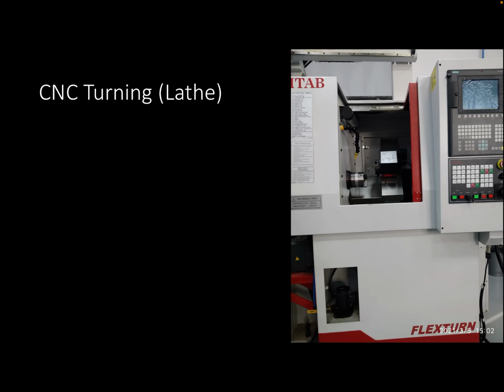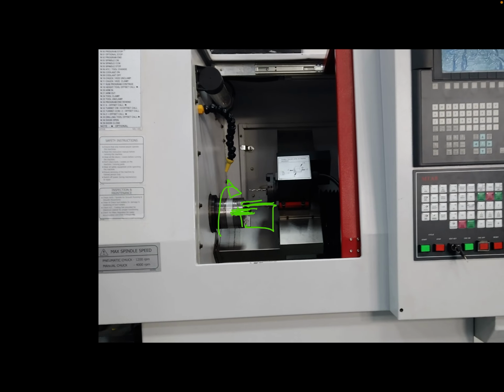So here you can observe a spindle, and here is the chuck. You have to mount the workpiece on this chuck, then this chuck will rotate, and hence this workpiece will also rotate. And here, using a single point cutting tool, here in this image you can observe a drill bit, but this can also be changed. This will hold the single point cutting tool, then you can easily perform the turning operation.